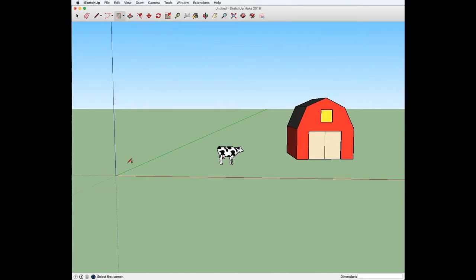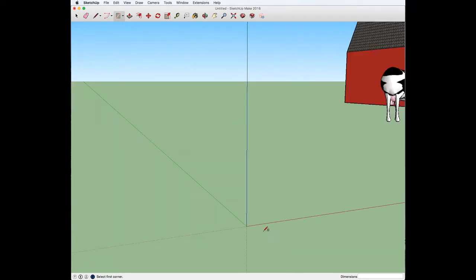I'm going to show you how to build this fence in Google Sketchup, and you can use these same ideas if you were going to build, say, an addition to your house, and you wanted to build a wall with studs in it, 16 inches on center. You don't have to draw each of those studs, and you don't have to draw each of those fence posts. There are ways to streamline that process with Google Sketchup, and I'll show you that now.